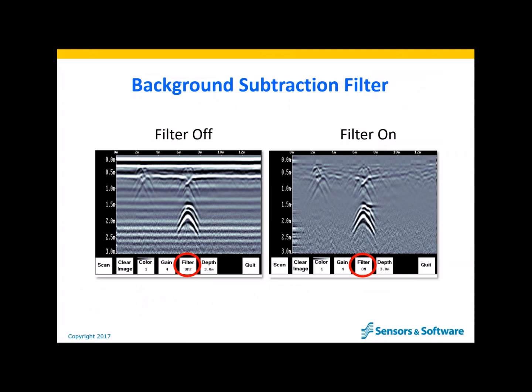The usual fix for coherent system noise banding in GPR data is applying a background subtraction filter. This filter can hide many sins, but I think that some GPR manufacturers are too dependent on software filters to fix poorly designed system hardware.